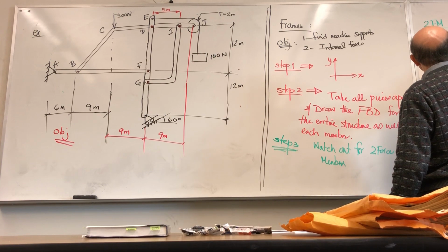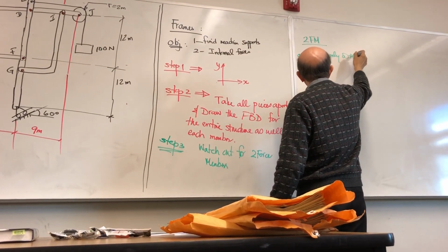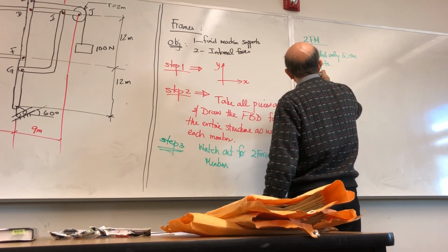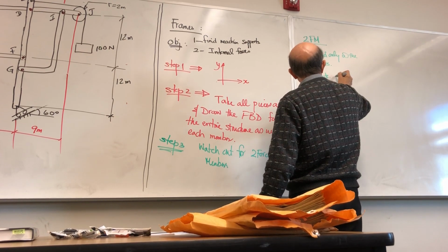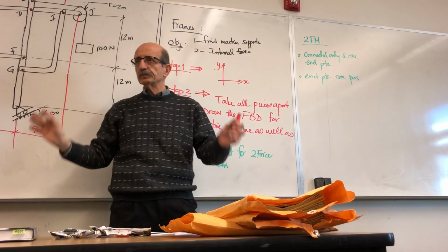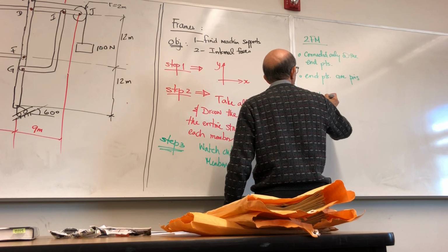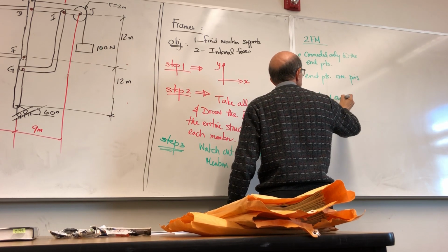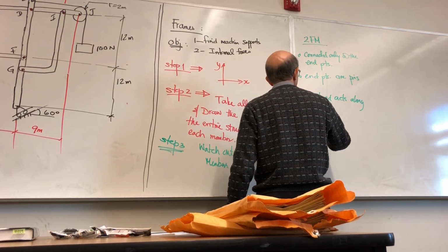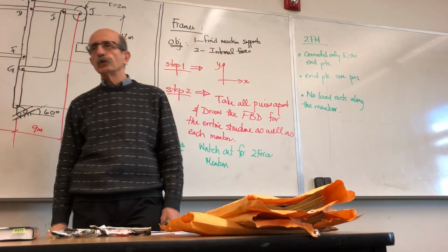Connected only at the end points. End points are pins. Cannot be fixed, cannot be anything. It's pins. And third, no load acts along the member. Only at the end. Okay? That was a 2 force member.